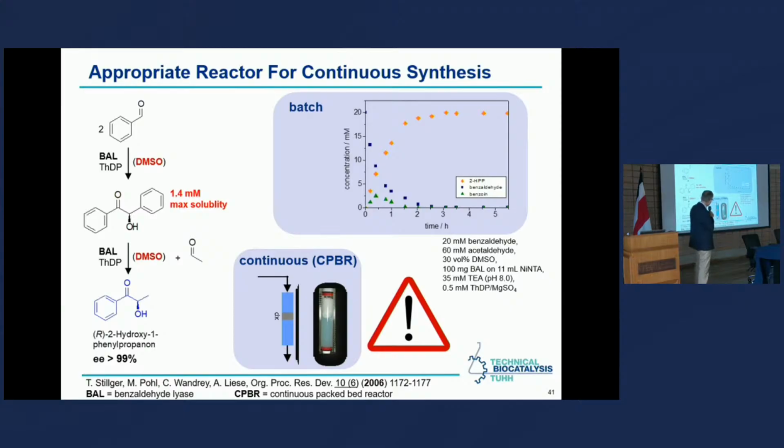This is the column with the immobilized enzyme. The pump had stopped working because of overpressure. And here in the beginning, this was operation, so inlet here, outlet there, you see white stuff in there. Something, the color has changed, it doesn't look as it is expected to look like.